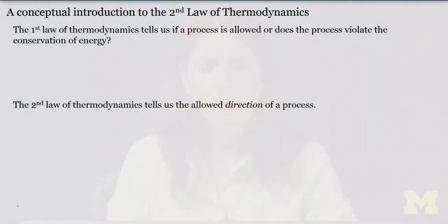Now, remember we talked about, let's just get our equations in front of us here, and that gives us something to talk around. So recall for our closed system, this is a conservation of energy, which says the change in the energy within that control mass has to be balanced by the net heat transfer and the net work transfer. And we had a couple of example problems where we said, well, can I have a system that has work transfer in and heat transfer in? And the answer was yes, as long as we have an appropriate change in the energy within the control mass.